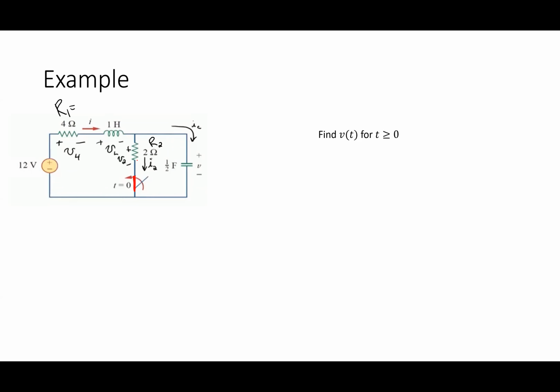My goal is to get the capacitor voltage. If they're looking for voltage, I normally do KVLs, where you go in the loops. Well, maybe. I do need to do a KVL here for sure. If you find the voltage across R2, isn't that the same voltage across the capacitor? It is. Yep. So do a KVL on the left mesh there.